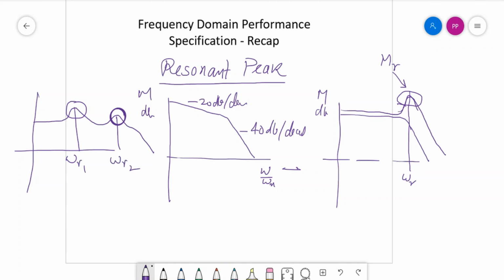This kind of situation is very common in control systems, or in any other system wherever the system order is more than one. When the system order is greater than one, such resonant peaks can be experienced. In control systems, it is a challenge for the control systems engineer to attenuate such a peak, because if such a peak is there, the system will have a sudden unwanted gain. This may cause instability of the system. That is why we keep studying the resonant peak of systems.